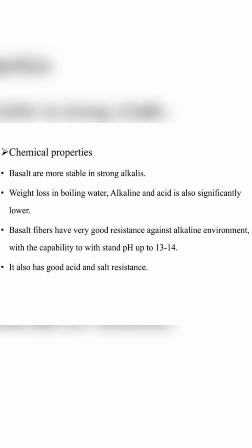The chemical properties include that they are more stable in strong alkalis, and it loses its weight on boiling water, alkaline and acid. Basalt fiber has very good resistance against alkaline environment with the capability to withstand pH up to 13 to 14, and has good acid and salt resistance.